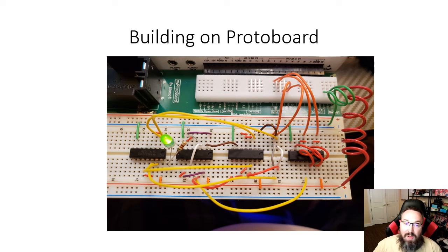There were a couple hiccups along the way because the NAND gates and the NOR gates are not configured in the same sort of configuration. What are normally the inputs to a NAND gate as far as pin settings are some of the outputs of the NOR gates, so they're flip-flopped. So going back and forth through the data sheets for the IC chips and making sure that that was working correctly was very important. But once I did that, I connected it back up to the computer and using NI Elvis once again tested it against the truth table, and the truth table and my circuit matched.